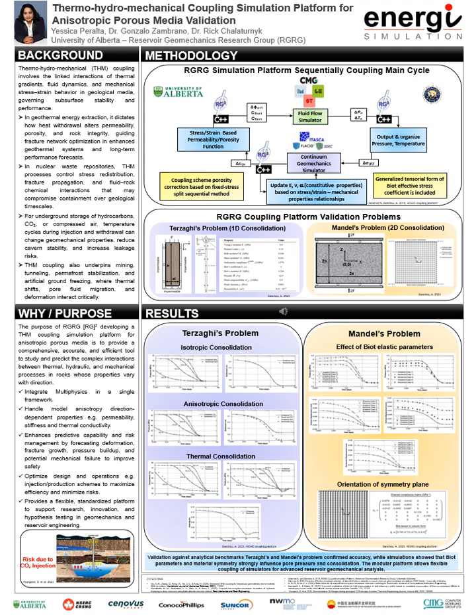The process repeats in short sequential cycles, with time steps chosen small enough that stress changes can be considered instantaneous compared to fluid diffusion. This guarantees both accuracy in capturing geomechanical feedbacks and conservation of fluid mass. This iterative exchange between CMG and FLAC3D continues until the end of the simulation.